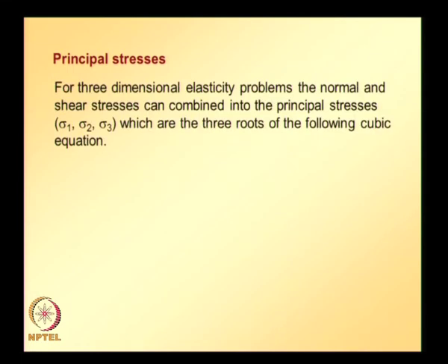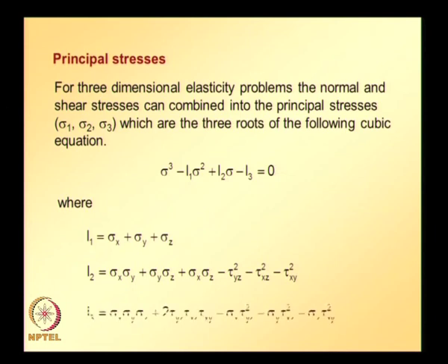For 3-dimensional elastic problems, the normal and shear stresses can be combined into principal stresses, which can be used for further applications in any of the failure criteria. So, these principal stresses are going to be the roots of the following cubic equation, which is actually in terms of stress invariants. I1, I2, I3 are called stress invariants, where I1 is defined like this, I2, I3.